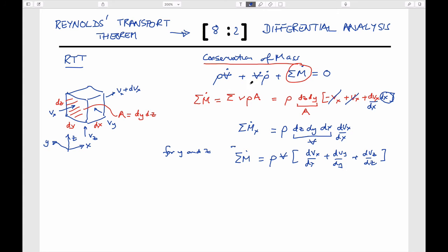If we look at the right-hand side of this, we could look at 2 cases. So if we look at the accumulation term, this is the rate at which fluid accumulates within the control volume. This is the rate at which it goes across the boundaries, in or out. And they have to balance. If we look at these 2 accumulation terms, the volume multiplied by the rate of change of density, or the density compared to the rate of change of volume, they actually represent 2 different systems.